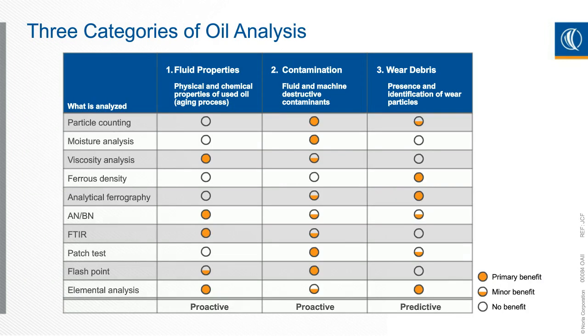If you've been performing oil analysis for a while, there's typically one thing you're going to look at first when you're reviewing the reports. You're simply going to look to see if the results are good or bad, right? And hopefully that's not the only thing you look at, but most reports will be laid out in a way that has an indicator towards the top suggesting this very detail. Usually there's some kind of shape or number or color or some combination of the sort. Green potentially meaning everything is good. Yellow, maybe we need to look at things a little more closely. And bad, that's going to be red. Something's wrong. Something needs to be changed, and maybe the oil needs to be changed. Maybe the machine is showing some kind of wear debris.